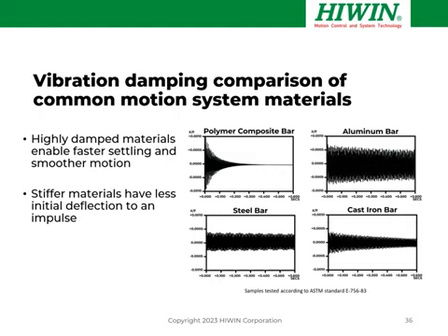Because the linear motor is capable of such high dynamic performance, it can induce high frequency vibrations into the machine structures. Vibration damping is an important characteristic to consider in this case. Vibrations can also come from external sources, nearby heavy machinery, or road and rail traffic, for example. Polymer composite materials, you can see, are the best in terms of damping overall, but they require a mold, so they're really only suitable for high volume production applications where the cost of a rather expensive mold can be justified.